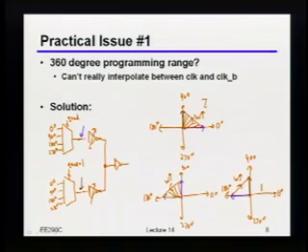You're absolutely right, but to understand why that's important, you have to keep in mind that the bits that are controlling this quadrant are physically different than the bits that are controlling that W, right? So imagine that when you cross that boundary, for whatever reason the bits that were changing the quadrant arrived earlier or later than the bits that were changing the W, right? So when I do this picture here, when I cross that quadrant, both of those bits have to change at the same time, right? Or rather, all of those bits have to change at the same time. That could very easily cause very big glitches, right?